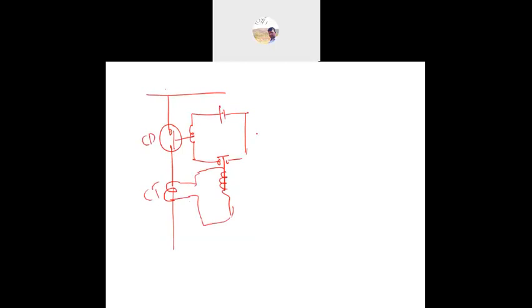When a fault occurs, at the fault condition the current is disturbed. If the current variation lasts only for 2 or 5 seconds and then it becomes normal, at that time the circuit breaker should reclose automatically. That depends on the nature of the fault.